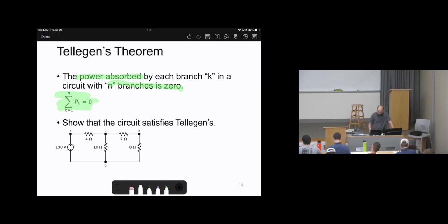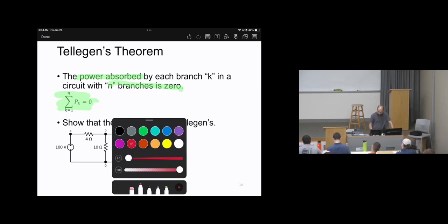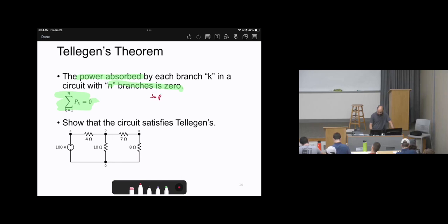Such that if an element is supplying, then the absorbing will be the negative of the supplying. So it means when you calculate the power balance, the supplying and the absorbing must equal each other. Since we let our reference be the absorbing, then whenever you see any supplying, convert it back to absorbing by putting a negative sign. And that's it.